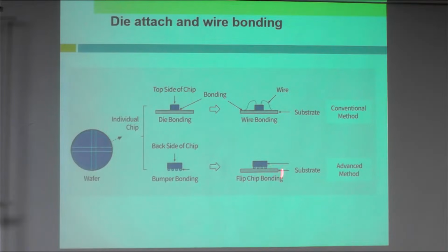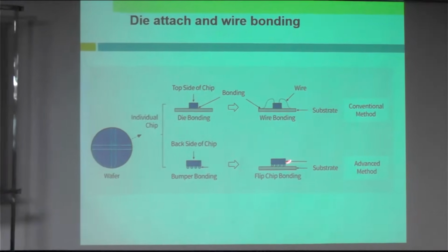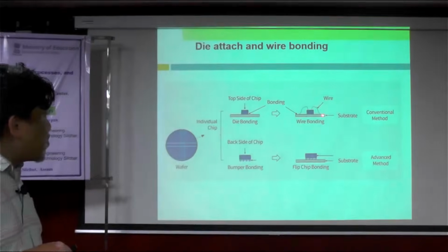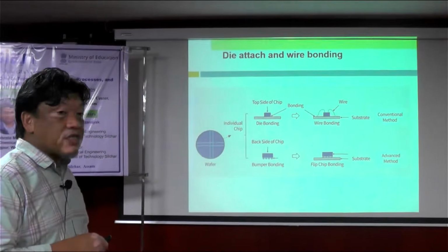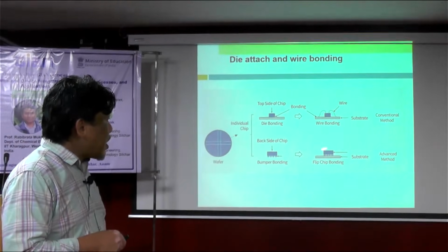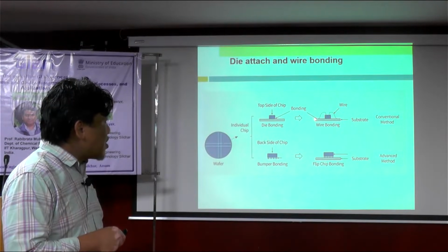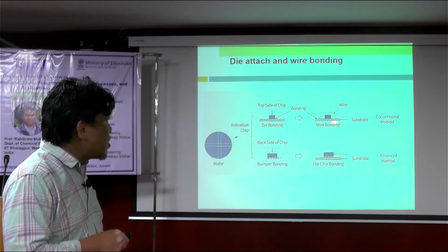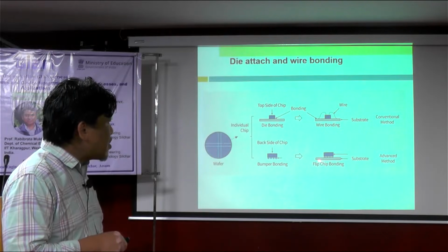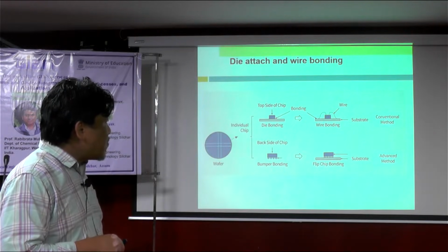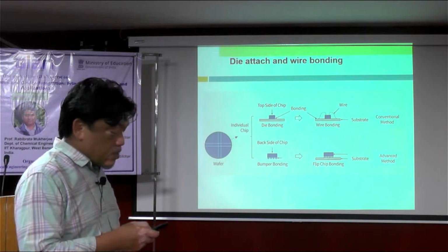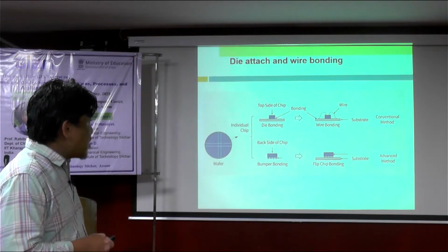Flip chip, as the name suggests, is about flipping the chip on top to the back, meaning you arrange your footing with a connector. So this flip chip will connect directly instead of using wire to connect the electrical circuit. This saves a lot of space, and you are only left with a small footprint for the device itself. So that is the difference with flip chip.